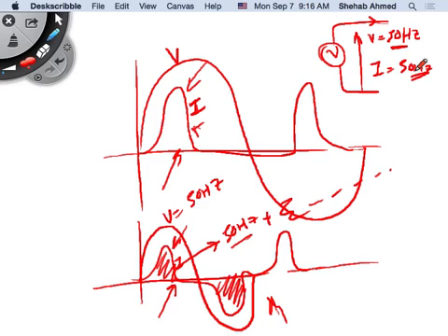So this is not contributing to motion forward. It's not contributing to pushing the load that you're trying to push. You're standing in your place. So there's no average power being consumed or transferred there. Same thing with the voltage and current. I have a voltage signal at 50 hertz. Because I'm feeding a nonlinear load, it is not responding with only 50 hertz current. It's responding with 50 hertz, 100 hertz, 150 hertz, all of these. And there's no voltage corresponding to the 100, 150, 200 hertz. The source is only supplying 50 hertz.